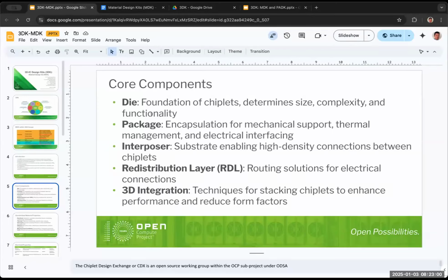For example, the tile, you will probably need the foundation of the tile. What other components build up the tile? I think the silicon, some of the dies, and all the material that makes up the bumps and everything. Same thing for the packaging as well. There is a substrate involved. Interposer, you have all this connectivity, like the wiring. And then the RDL, definitely, is the layer on top of the wire, on top of your chip design, and then the 3D involves all those vias and stacking, etc.